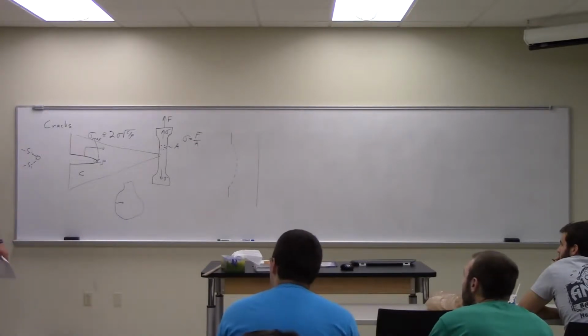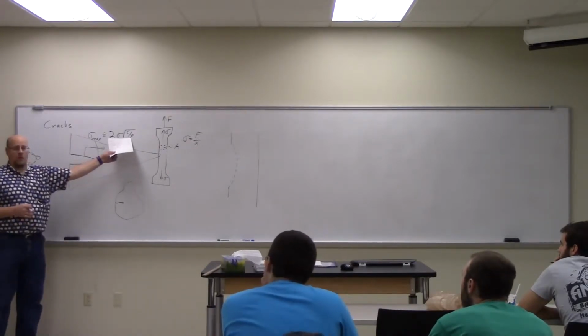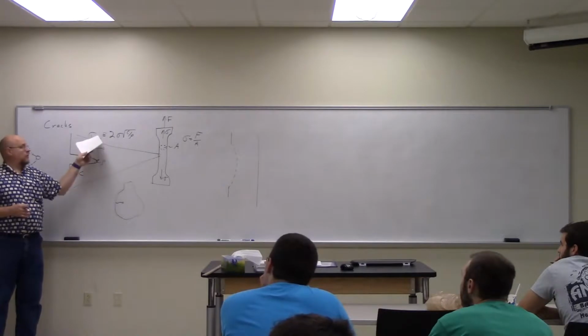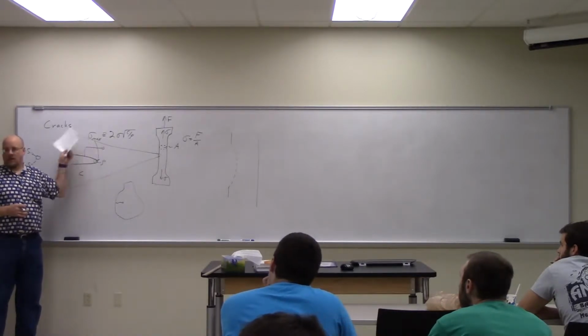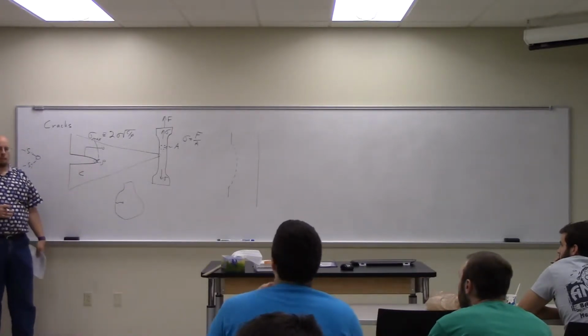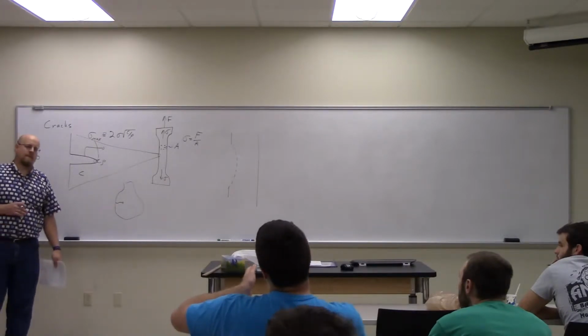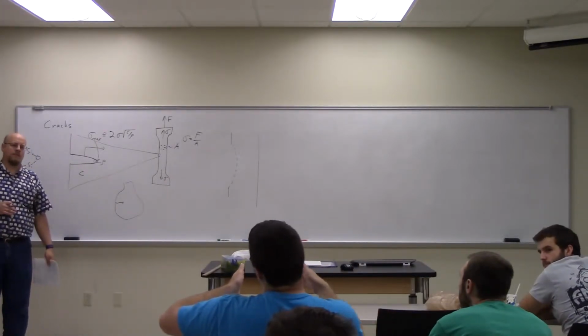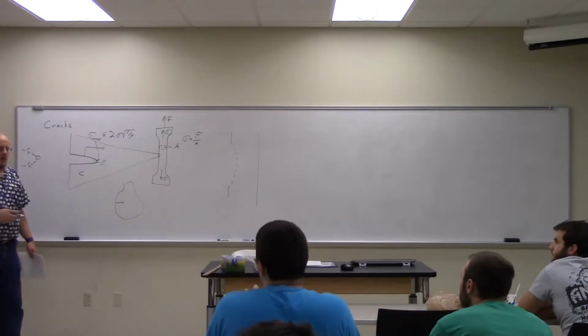The purpose of drilling the hole is to increase the radius so that you could reduce the stress and keep the crack from growing. So you're just kind of coming in from, I'm assuming it's curved, you just come in from this curve and do it, or you just come along.